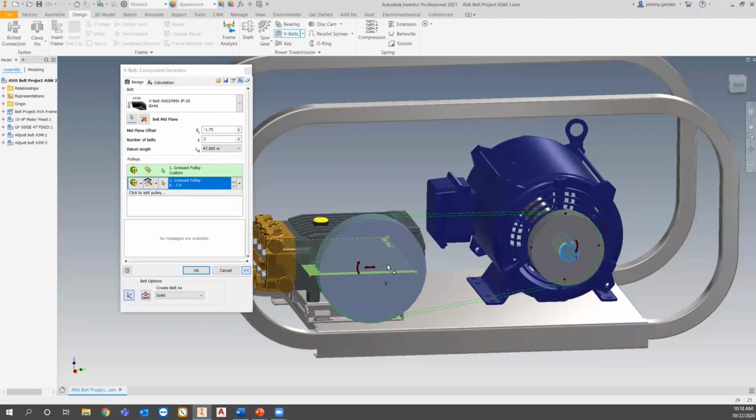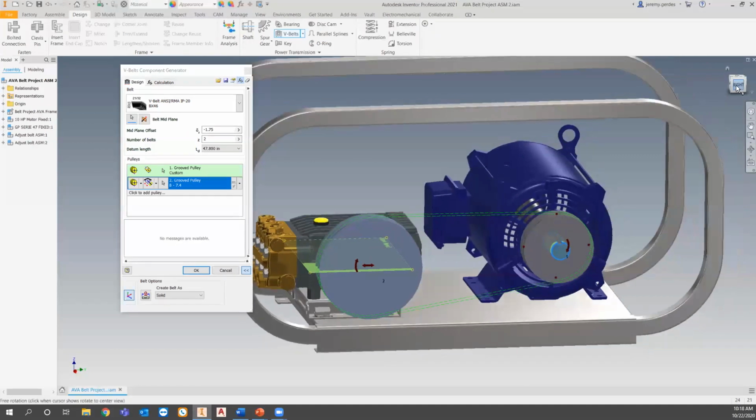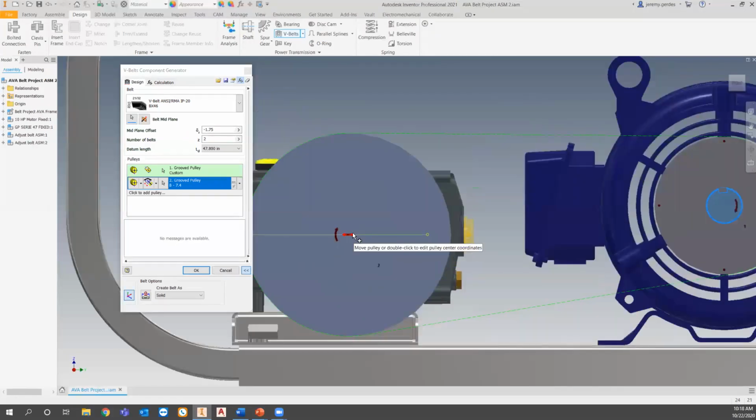So, sorry, real quick, Jeremy, too. This is a question that came in. So it's only sliding, like free sliding, based on like a length of belt you can use? Yes. It's going to lock it into the belt lengths. It's only going to slide it from a BX38 to a BX42, whatever the belts are in the system.